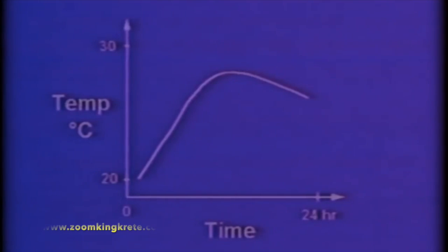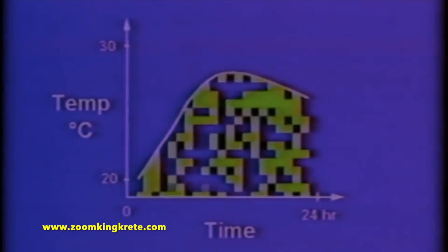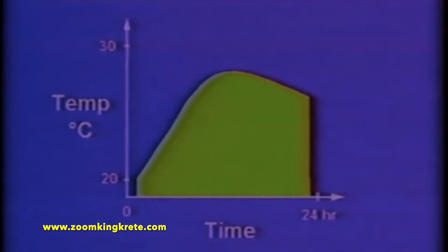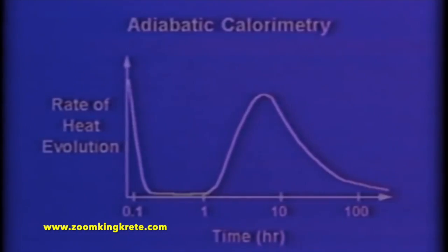The results of this experiment can be plotted as a curve of temperature versus time. The area under the major peak can be related to early strength development. The initial dissolution of cement produces a short release of heat, shown by the first peak in the calorimetry curve.